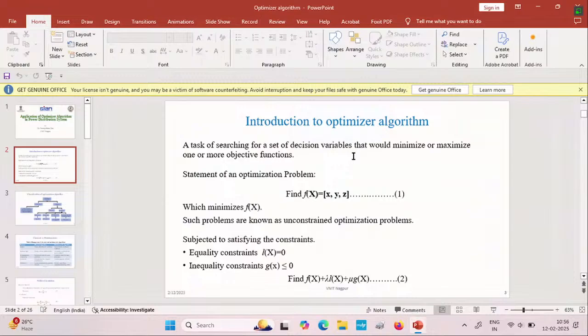Based on that known load, we are supposed to calculate the current, and this current calculation is done from the dead end node. Based on that we calculate how much branch current is on each branch, and in the next step we calculate the voltage, from the first node, second node, up to the nth node.